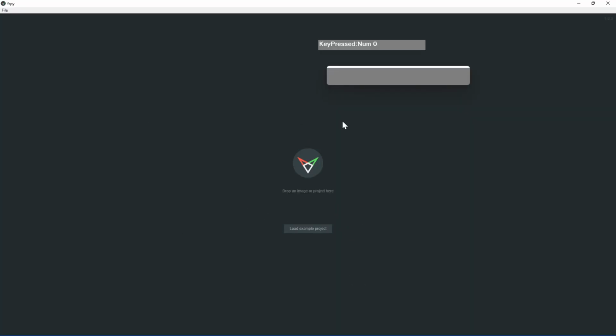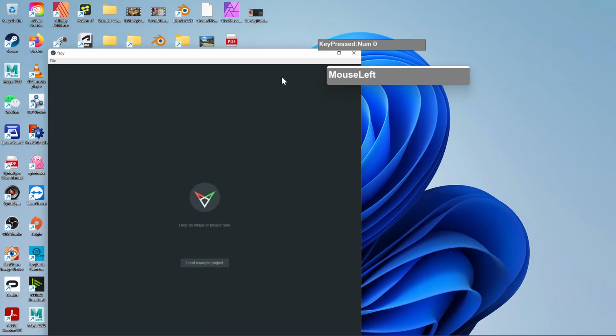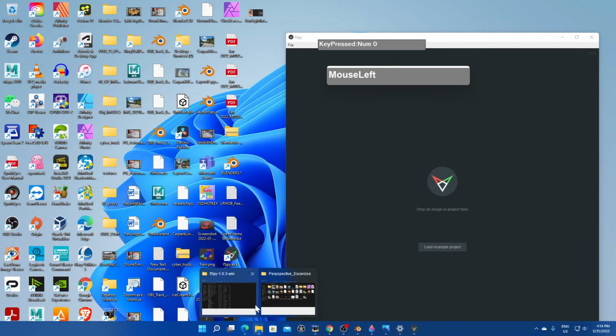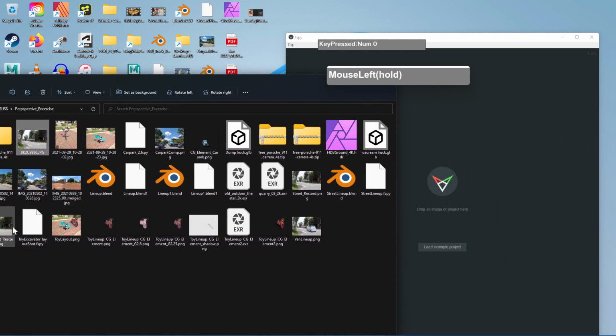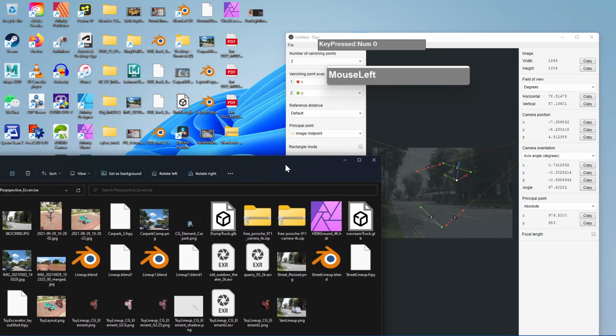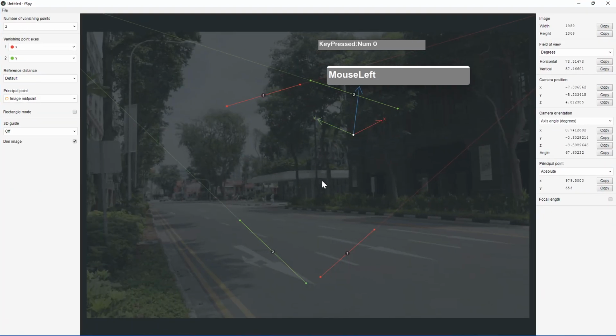Okay, and you just need to drag and drop the photograph into this shot. So I'm going to drag the resized version into fSpy, and then I'm going to do my lineup. So fSpy is pretty easy to use. You can drag these lines and find the straight lines that form the disappearing horizon. And because this is a picture of a road, we can easily find out what are the straight lines that converge to form the disappearing point, to form the vertices, or rather form the perspective.